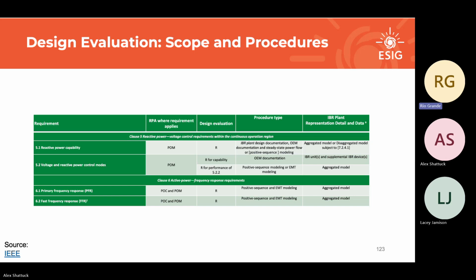So I can test it on the real plant. They send a signal, basically just give me your maximum reactive power capability, and sometimes stuff trips off. Sometimes the end turbines trip off, and then you have to recreate that problem in this disaggregated model, or whatever the most detail you can get, and try to mitigate those things. That can be an inverter control to not push themselves out of voltage range. It could be retapping GSUs, the little taps on the step-up transformers, differently in different places around the plant to keep things about right.